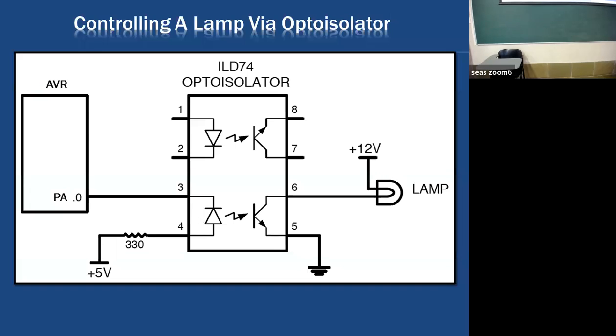And anyway, we are not receiving light here. We are sending light from here. So any problem on this side of the circuit will not impact this. Generally this side is more expensive. We save our controller and the controller board and so forth. So we are isolating two things. Another thing is the voltage. We have 12 volt here, for example. This is operated by 5 volt. So we can have higher voltage. So it isolates two different voltage levels.